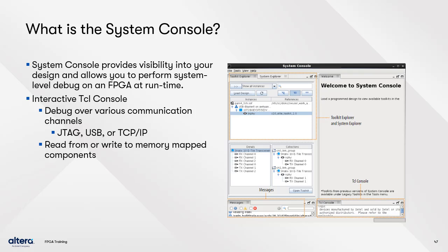System Console performs tests on debug-enabled Altera FPGA IP. Perform board bring up with finalized or partially complete designs. Debug transceiver links, memory interfaces, and Ethernet interfaces. You can automate runtime verification through scripting across multiple devices. Integrate your debug IP into the debug platform, and perform system verification with MATLAB.